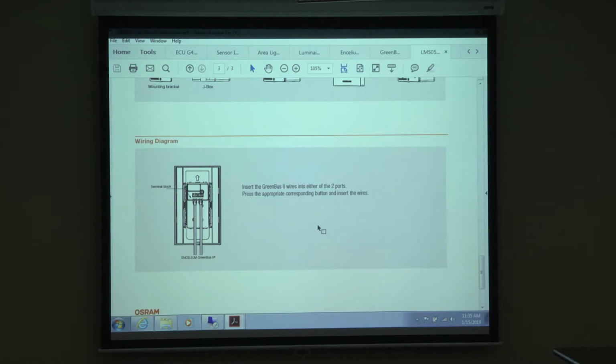So the best thing to do is not to T-tap. If you're going to T-tap, keep it to a minimum, and know where it is. Otherwise, you go crazy trying to figure things out when something goes wrong, right?